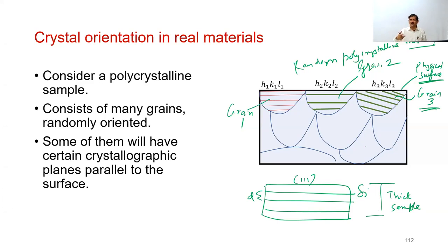Sorry, I kind of jumped the gun to tell you about the concept of microstructure of a material. But in order to explain X-ray diffraction, this becomes a bit essential. Suppose we have water and we are cooling it below 0 degrees centigrade. From the free energy transformation, ice will become the preferred phase. So ice crystals will start growing in water at random locations, and then they will start impinging upon each other. All those ice crystals have the same crystal structure, but they are oriented differently in space.